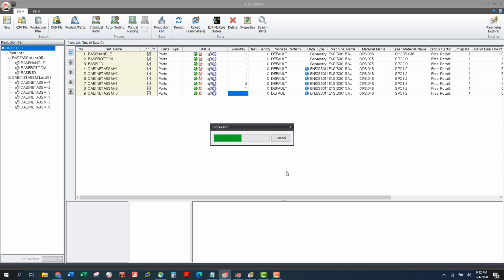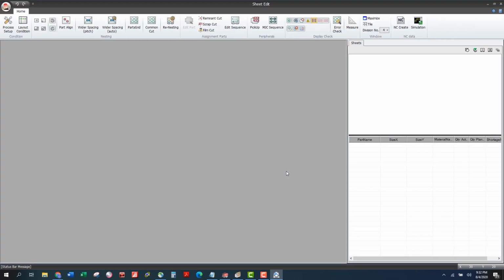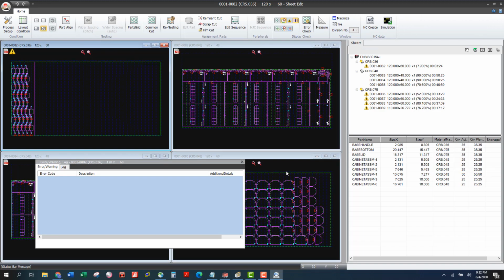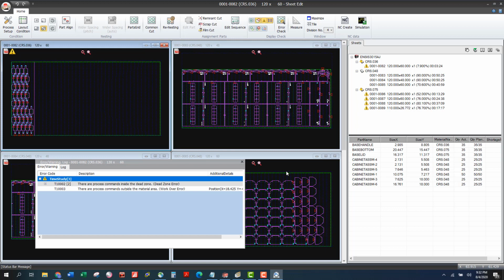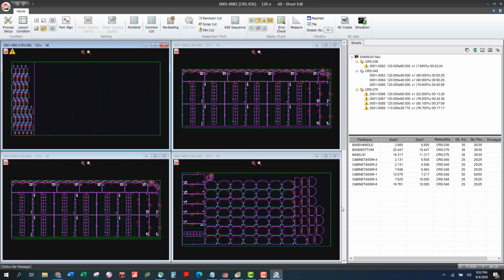It's also going to, on the laser, look at your slat locations and such. And if there's an opening that is at risk for tip up, it'll slug destroy that opening or put tabs on it, depending on what your preferred method of manufacturing is. It's going to generate all of our NC code, nest all these parts out, apply our remnant cuts, a number of different features all happening at once when we do that auto nesting.